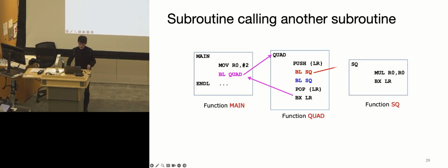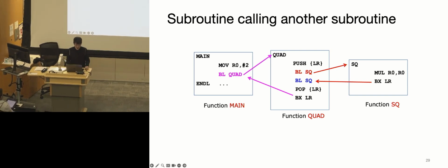And this is a quick graphic to show how the subroutine calls happen. Basically, you have a branch, and then that points to a function, and then we store whatever needs to be stored. If we have multiple subroutine calls, even the link register is not enough to hold, because it can only hold one value, right? So even the link register will need to be pushed onto the stack in order to have the program able to find its way back through two layers or more.